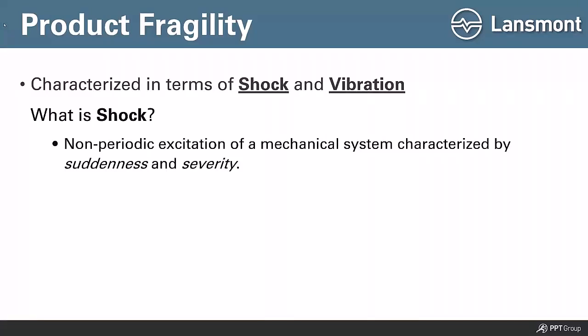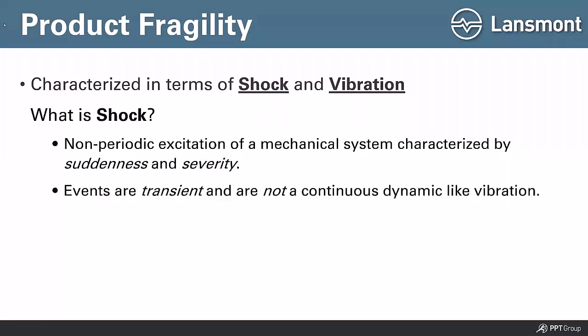When we talk about shock, it's a non-periodic excitation of a mechanical system, and it's characterized by its suddenness and severity. So thinking in terms of shock and/or vibration: shock is big. Shock is quick. It's much greater intensity than you would normally experience in vibration. So it's severe, and it happens quickly. They're transient events. They may or may not occur, and when they occur, it happens and it's over.